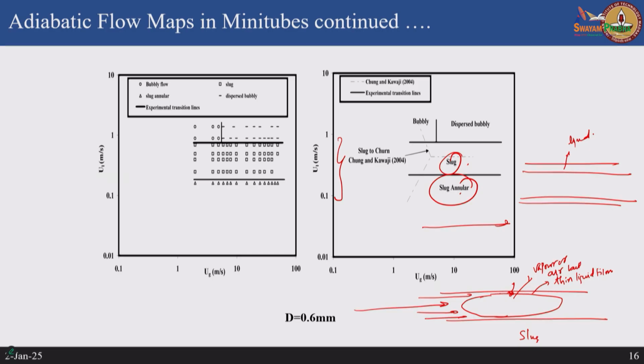So, it will be more useful for improving the heat transfer rate, and just because it is evaporating, this is not going to run out very fast, because there is a continuous supply of the liquid due to the advection that is bringing in. So, the thin film will continue to exist, but due to very high and rapid evaporation rates, you will get very large heat transfer coefficients. So, therefore, the slug flow or the annular flow regimes are actually sometimes very useful in terms of improving the